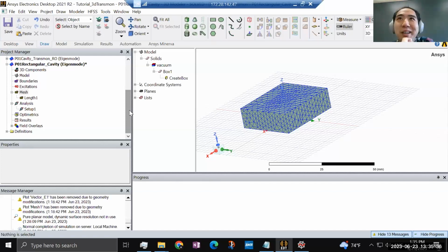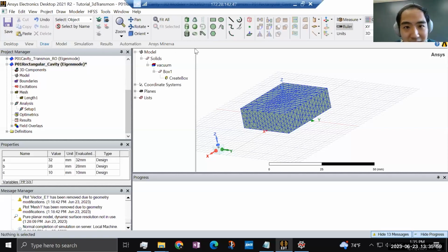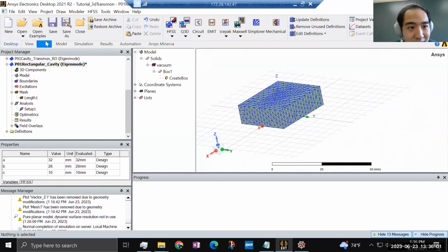Good question. I don't really know. We usually model a superconductor just as a perfect E boundary condition, right? Because in the microwave frequency range, the electric field and magnetic field are kind of the same thing. So when you model it as a perfect E boundary condition, which, okay, it's better if I just draw it.